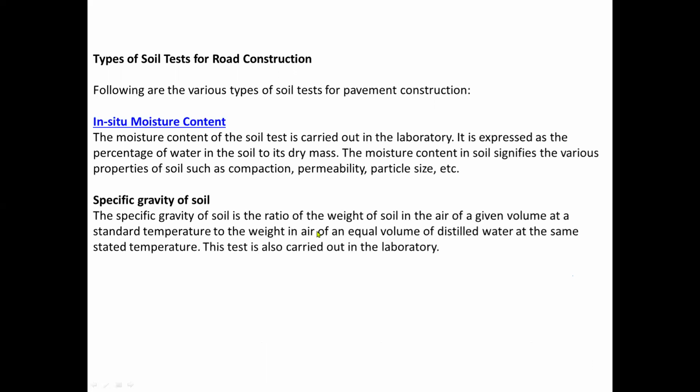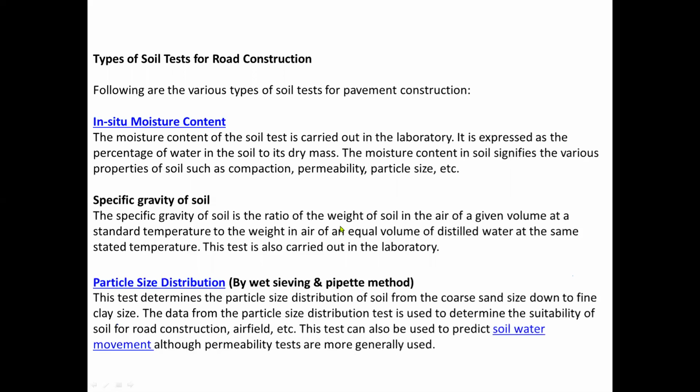Specific gravity of soil is the ratio of the weight of soil in the air of a given volume at a standard temperature to the weight in air of an equal volume of distilled water at the same stated temperature. This test is also carried out in the laboratory.